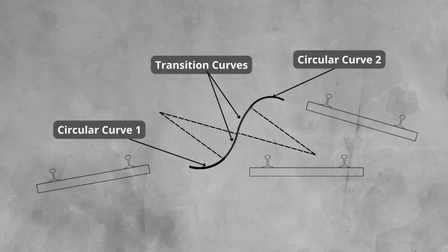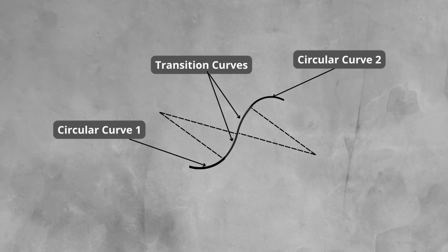rail. Another way to understand this is to treat the cant on the first curve as positive, and due to the change of high rail, the second cant must be negative. So, a minus and a minus equals a plus. The other point to note, when working with reverse curves and transitions, is the point known as the reverse point. This is the point at which there is no radius or cant on the track. From this point, cant and radius is increased, but in the opposite direction.